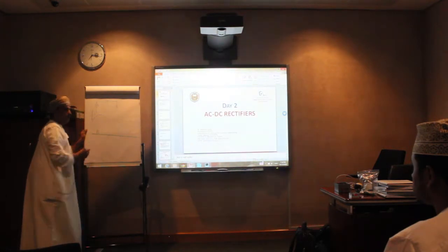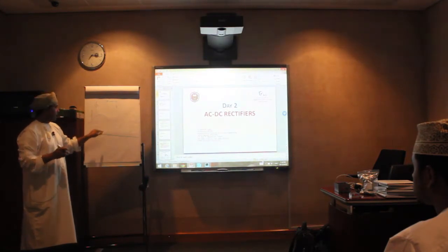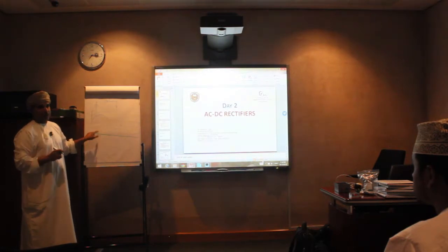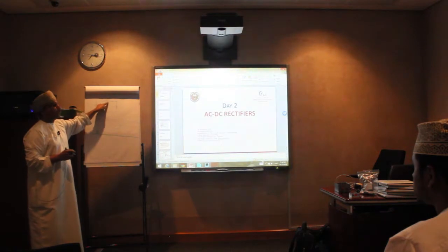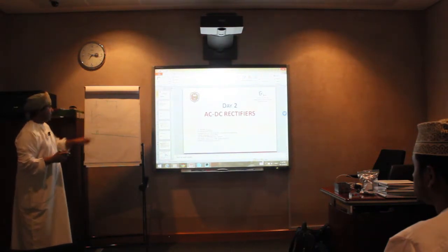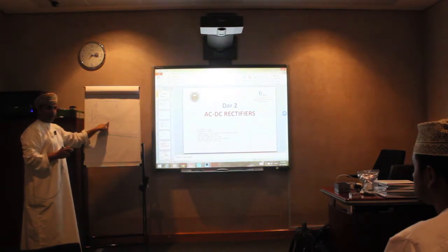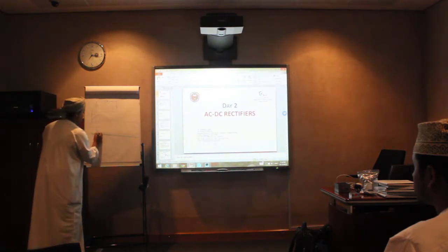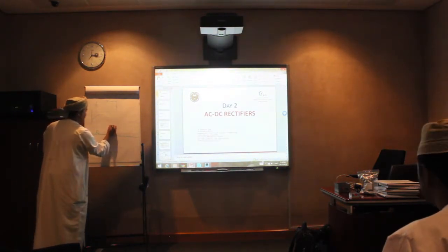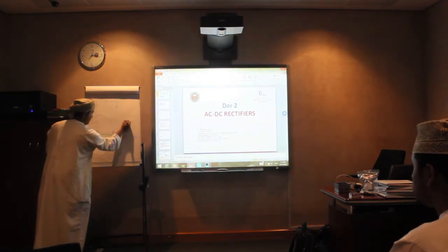Once it's forward biased, you don't need to keep the signal on. Just send it as a pulse, and once it turns on, that's enough. It will keep on until the current goes to 0. So with a resistor load, it will turn off at this point, like the diode. So if I send the signal here, and then the same signal here, at the same point.